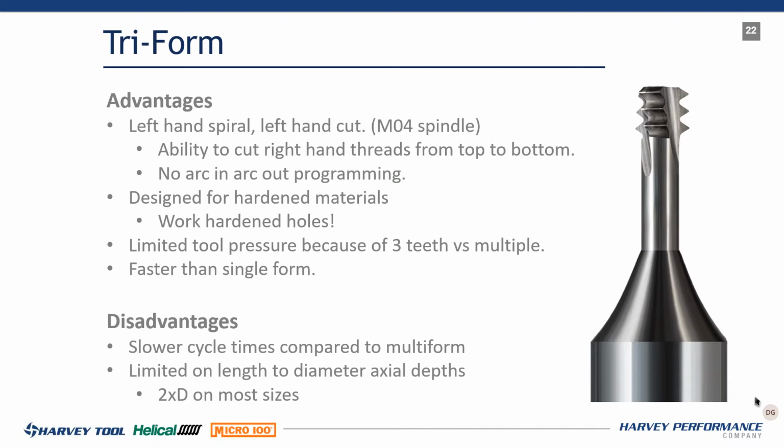But with this tool, you're starting at the top of the tool. So basically what you're doing is a helical ramp, a helical interpolation with the pitch, whether you buy a 20 pitch or a 32 pitch, from the top of the part. So basically come down on Z, move over, helical ramp all the way down to the bottom of the hole, and come out of the hole. So the programming is a lot easier with this tool.